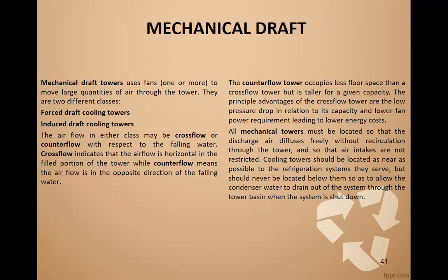The counter flow tower occupies less floor space than a cross flow tower, but it is taller for a given capacity. The principal advantages of a cross flow tower are the low pressure drop in relation to its capacity and lower fan power requirement, leading to lower energy costs.